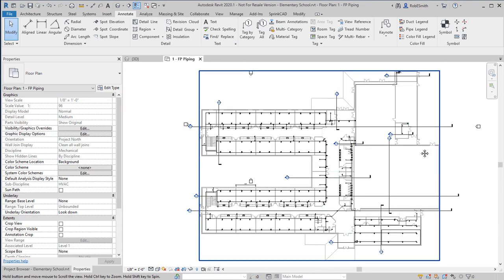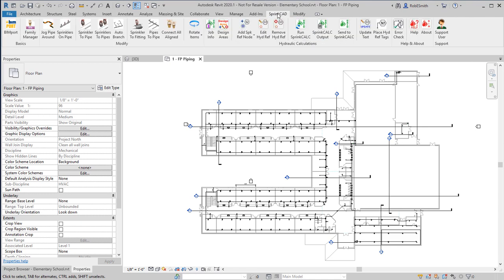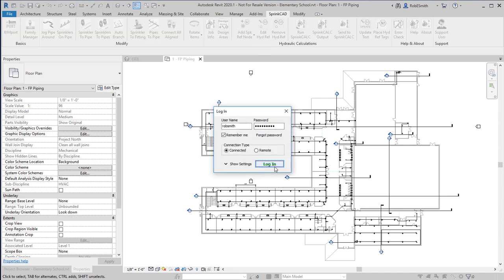So in order to generate an NFPA 13 style report, all I really need to do is identify a source point and identify the flowing sprinklers. But all of that information lives within the context of a design area. So I'm going to create this design area.